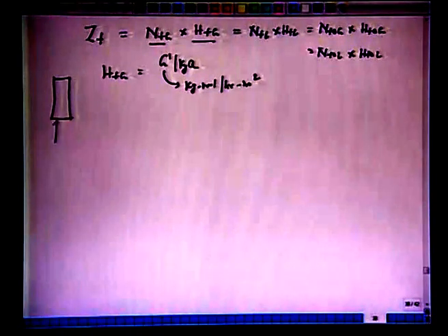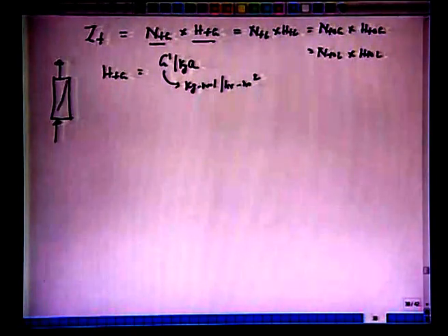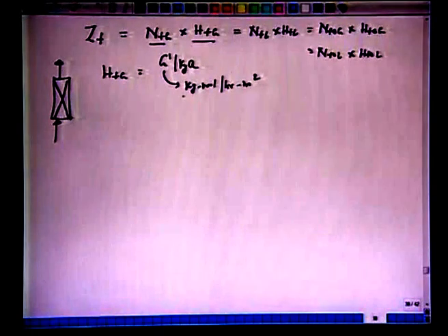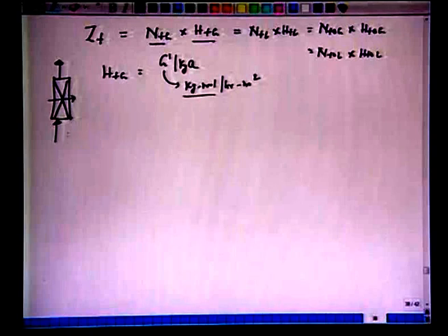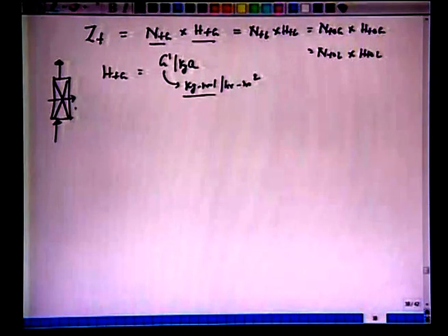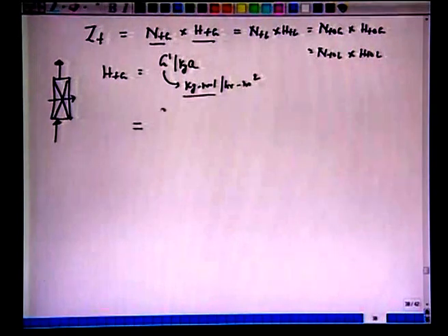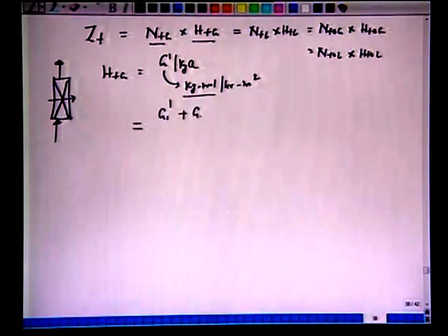So, as the gas passes through the packed bed column, the flow rate of the gas, this kg mole per hour per meter square, changes as there is a mass transfer from the gas phase to the liquid phase. So, as a very good design or optimum design, one should work on the average of G1 and G2, at the inlet 1 and the outlet 2 of this column.